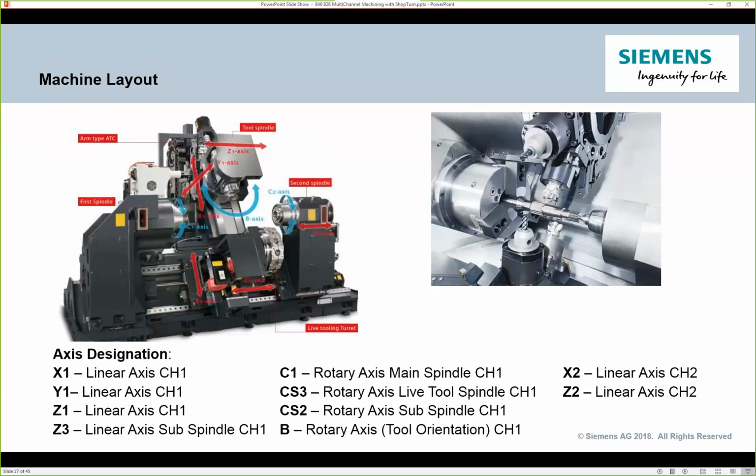Now the spindles are interesting because they'll be assigned to a specific channel, but they transcend channels. So you're going to be jumping between spindles, running either spindle, as far as the work holding spindles are concerned, from either of your two channels. So don't get caught up on the fact that the main spindle is in channel 1. That doesn't mean that channel 2 can't run the main spindle. The only time they're separate is what's unique to the turret or the work holding, the physical tool carrier.